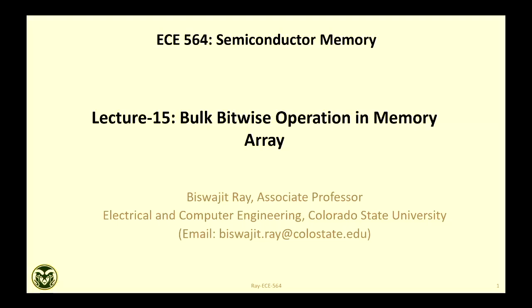We'll start with in-memory computing. Yes, memory, we know how to store data reliably, but can I use the same fabric for computing purposes? That is not done today, but there is a lot of interest and motivation for doing that. So we'll talk about some of those techniques, specifically for bitwise operations, which are more like digital computation. You want to do bitwise AND, bitwise OR, bitwise NAND, NOR, XOR, XNOR. Those kinds of operations we'll be talking about today.